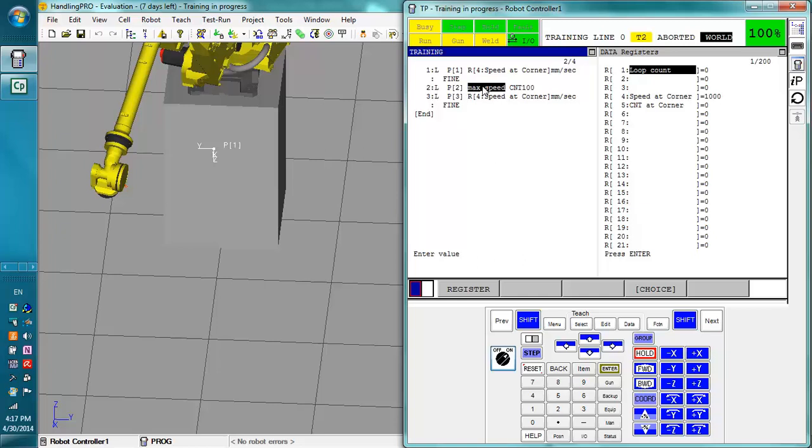The reason this happens is because you can go faster than 2000 millimeters per second in joint mode, but linear has to have a maximum to give you. Still, there is that possibility that just due to the actual spot it's moving in, it's able to go a little faster. So if you ever need to speed up the robot, you can experiment with this max speed option.